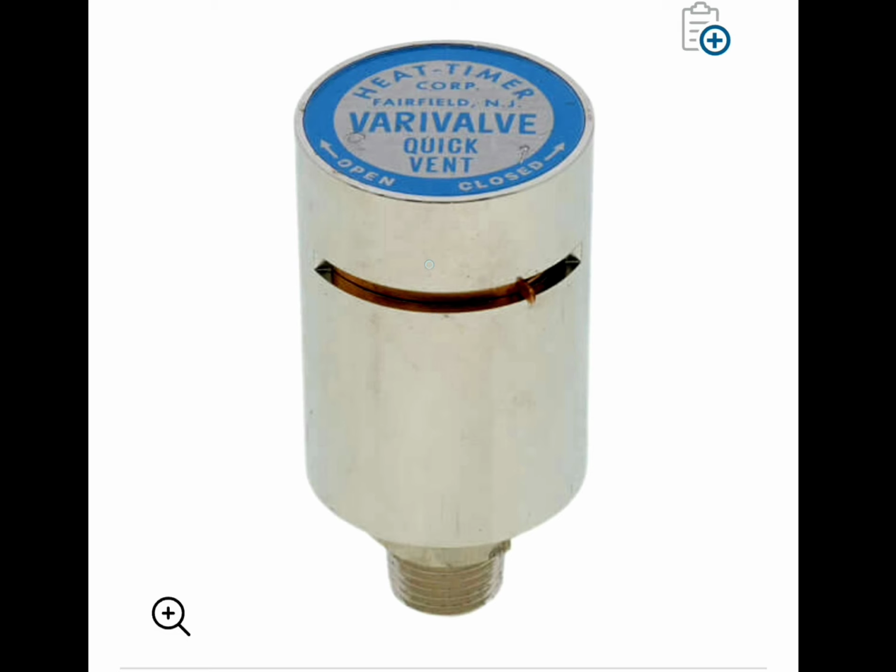And once again, I do not recommend that you use these for steel convectors. The first reason is that the radiator builds up with water, and since the convector has a much smaller water and steam capacity, if there ever was a situation where water got inside of it, it's going to fill up a lot faster. Reason number 2 is that the valve body is so thick and so heavy, it holds its heat a lot longer than your standard air vent would. And your steel convector will actually begin to cool down, based off of its construction, a lot faster than this air vent, leaving you with slower heat times.